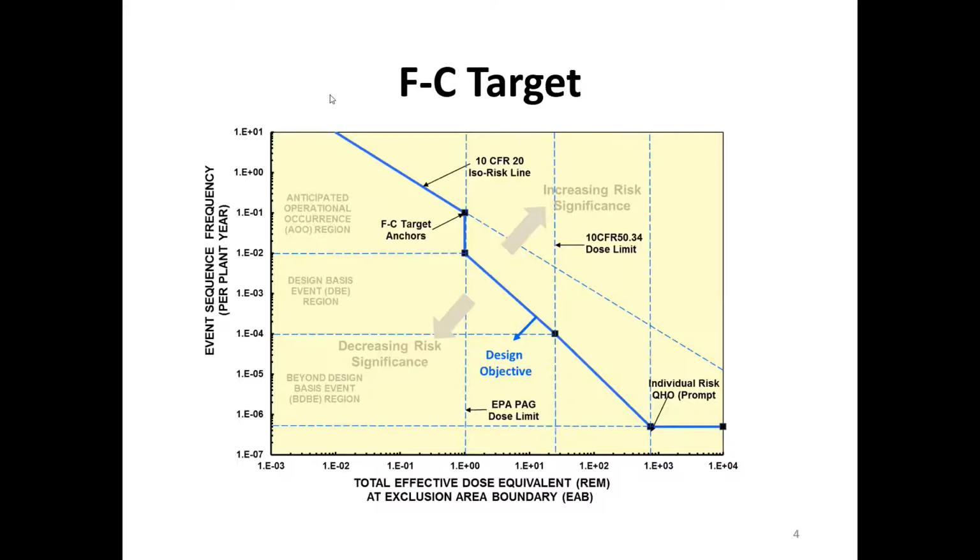Remember, level 3 is the impact on the individual or collective dose after dispersion. I mean, after the containment fails, and then dispersion, and then going to the public. This is level 3. I understand that this target performance corresponds to PSA level 1, that means core damage frequency.